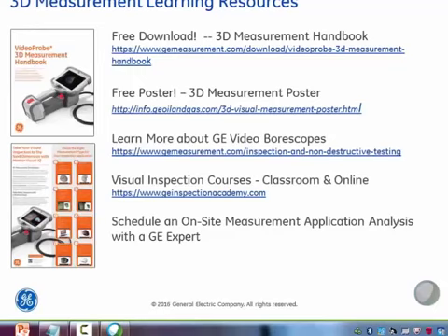So as we discussed in that section, this is primarily a concern when you're making very small measurements. And in those cases, if you want to get the best results, you really need to get as close as you can to the surface. And again, the 3D point cloud view is sort of your best tool to assess the accuracy that you're likely to be getting. And you want to look for low noise in the areas outside of the indication and a clear signature of that feature.